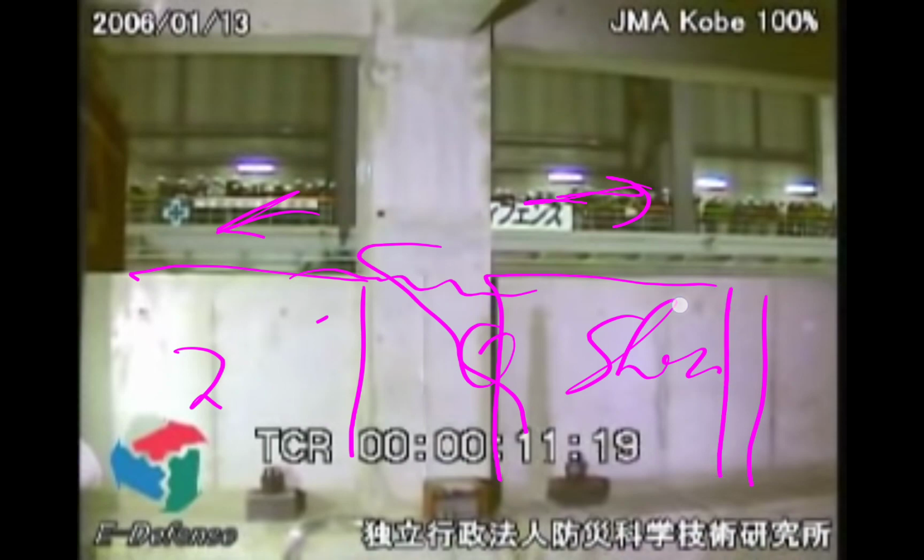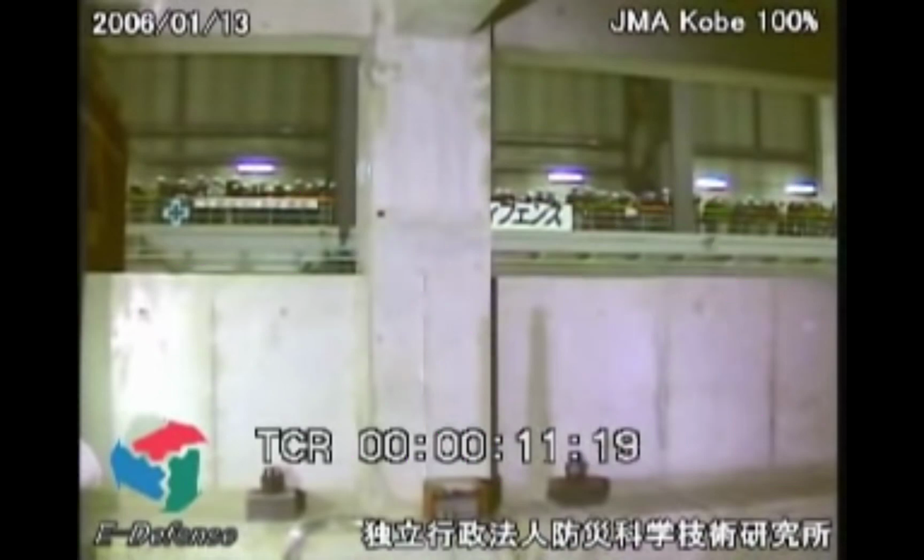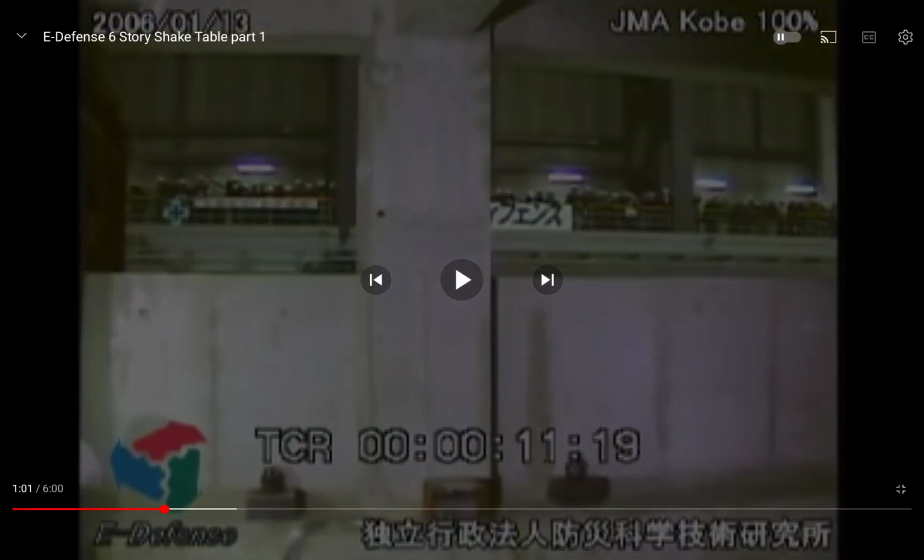This wall has reinforcement, let's say like that. This reinforcement is here, and then it has a dead load on top of it to keep it more stationary. There's no dead load on top of this one. So they're going to shake it, let's say west and east, with multiple little rotations too, but this is the problem with that connection in this case. I see it repeatedly when I see connections like this, looking at my shake table failures. Let's watch it.